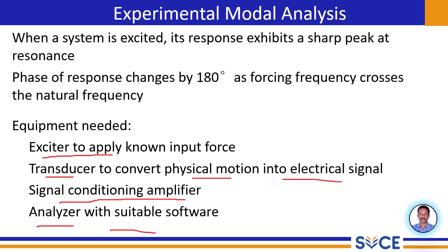So this combination of equipment allows us to introduce a controlled dynamic environment to the structure and precisely measure its multiple point response. By analyzing this relationship between input force and output vibration in the frequency domain, we can identify crucial modal parameters that can describe the structure's dynamic behavior.